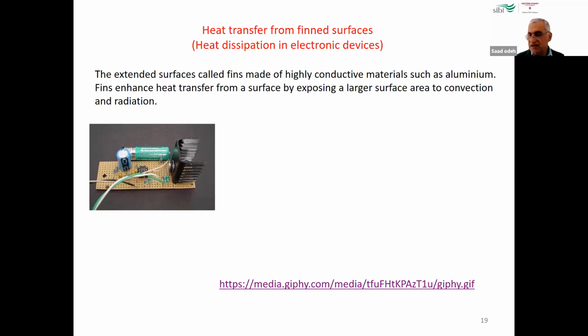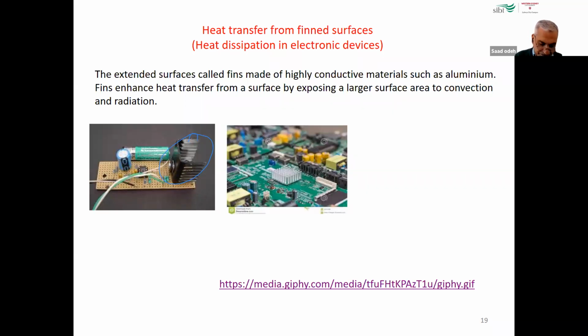So you need to cool it always, and that's why if you open these devices, you will find the IC attached to a surface with extended surfaces, the one that you can see here in the middle. Can you see this one? Under this surface, there is an IC, and this is an aluminum block with fins, extended surfaces, and these fins actually increase the surface area of the heat transfer.